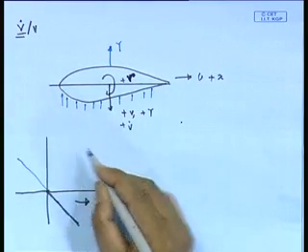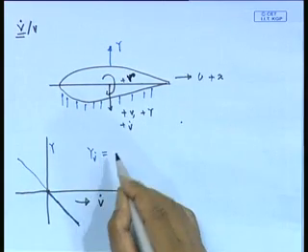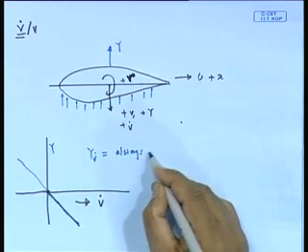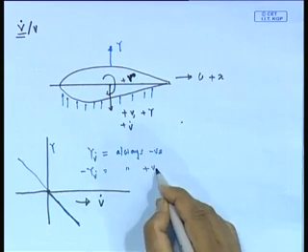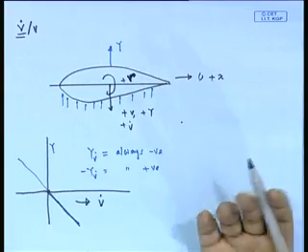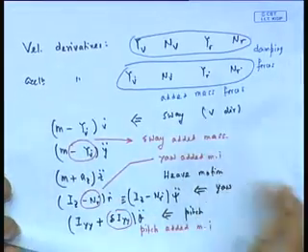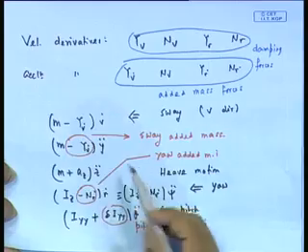So, then what happened? This is Y. So, what happened to Y_v̇? It is always negative. So, actually minus Y_v̇ is always positive. In fact, that makes sense, because minus Y_v̇ is the added mass, as I have just found out in the earlier talk. Minus Y_v̇, added mass, of course is positive. So, interestingly what you find out, Y_v̇ is always negative, that is one.